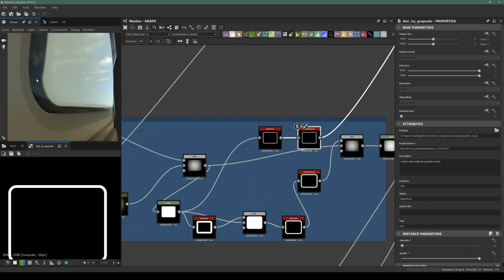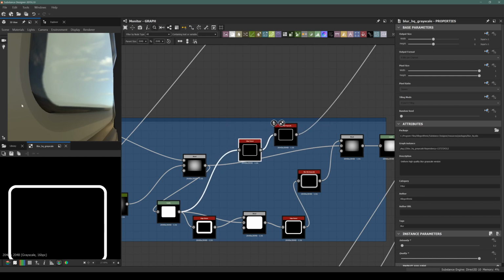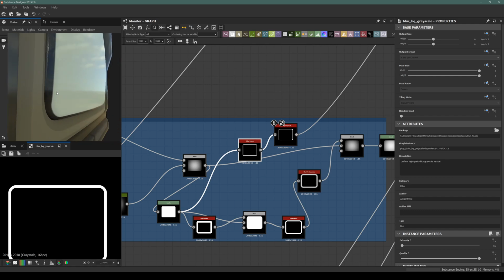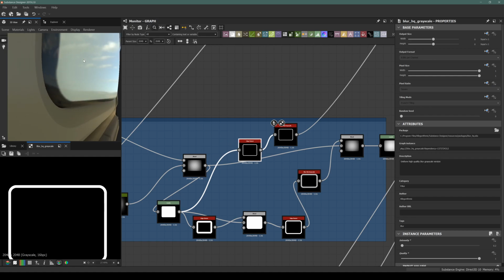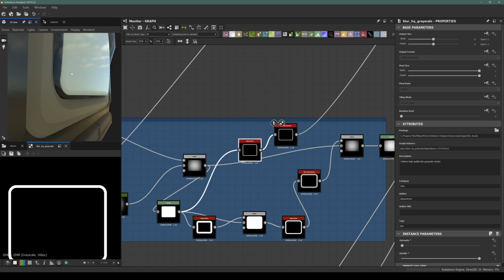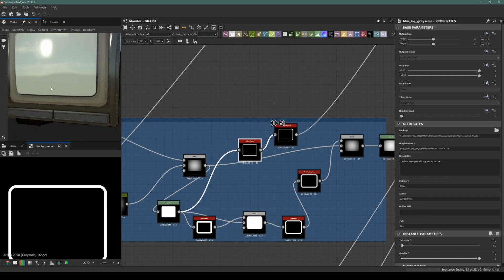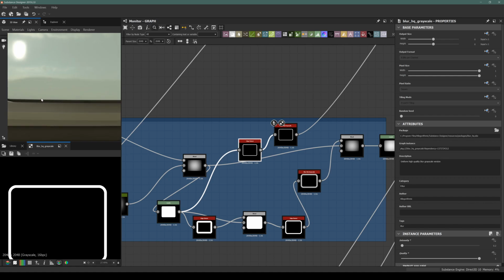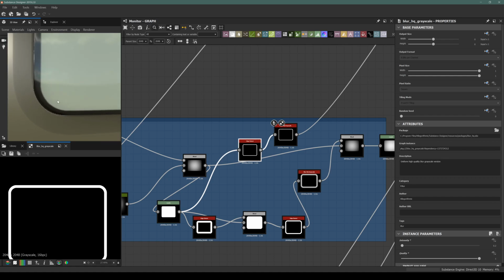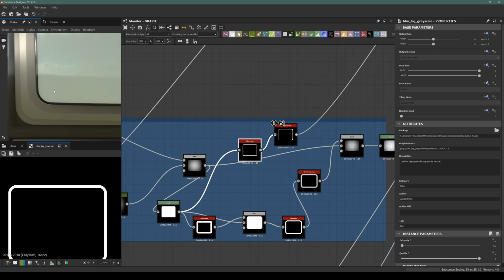Let's increase the blur a little bit to get a better result here, because it's the height displaced area, so we get results in lower resolution on these areas, because the polygon here is using the UV area much more unbeneficial than the rest of the layout of this shape, because it's projected from the front view, so there is skewness on this area, so the polygon texture is not distributed here as the rest of the model, so the sharpness goes away, and also we have a skewed result.